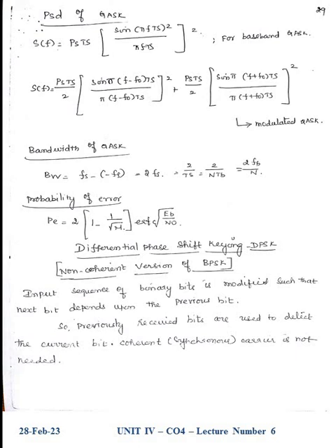It is also a common form of phase modulation that conveys the data by changing the phase of the carrier wave. For example, in differentially encoded BPSK, a binary 1 may be transmitted by adding 180 degrees to the current phase and a binary 0 by adding 0 degrees to the current phase.